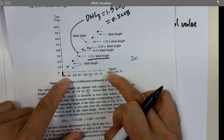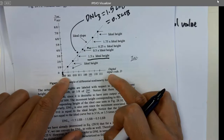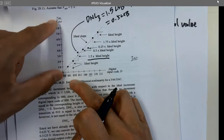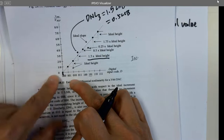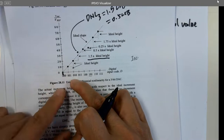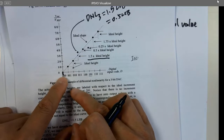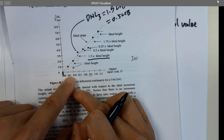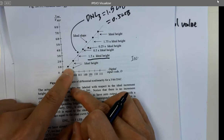So it converts digital signals to analog signals, right? It's a 3-bit DAC, so that makes sense. The inputs are digital numbers, and these are the outputs, analog voltages. Whenever this jumps, if the input is 0, you're expecting 0, no problem. But whenever it jumps to 1, you're expecting a 1 LSB output from the analog voltage.